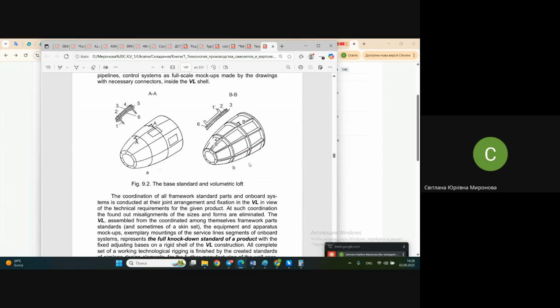What for? Either we need to produce one more assembly jig of the same sizes and shapes, or we need to check, to inspect an assembly jig somewhere in a shop. And in this case, how may we inspect it? We bring the mounting standard, install it in the assembly jig in the position that it had when the jig was first created, and compare the deviation of the assembly jig locators from the mounting standard contours. Such kind of inspection with a natural carrier of sizes and shapes.